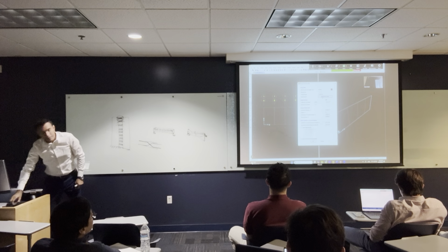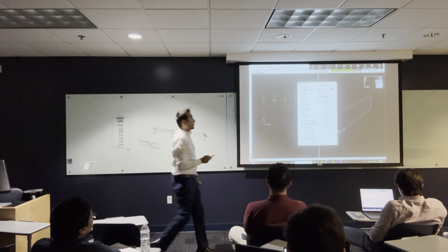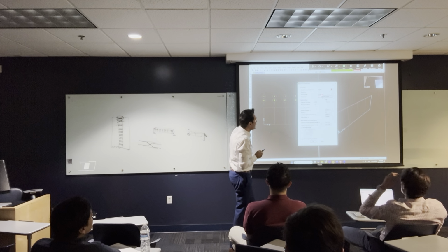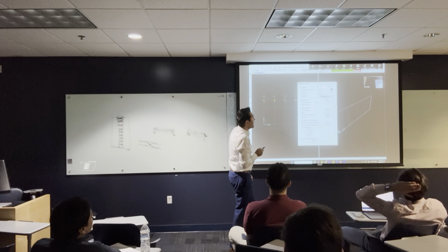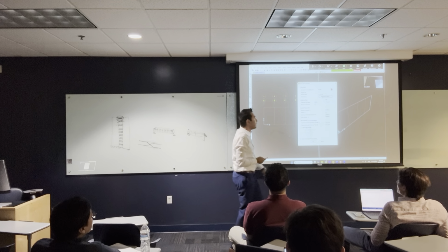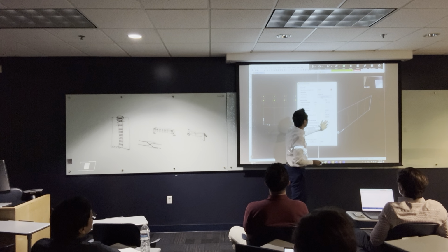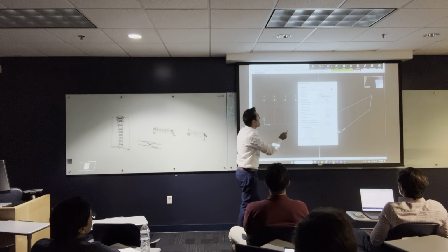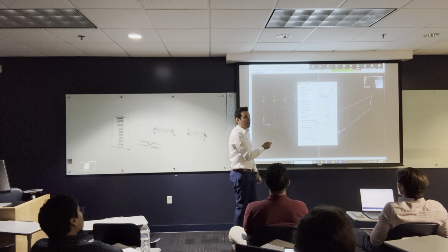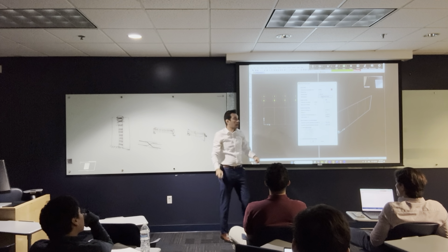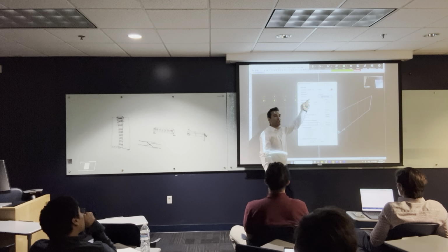You're going to find out that the material name is called 4,000 pound per square inch. The material grade is here. But if the name says that, this doesn't mean anything. Let's say you adjusted this to 5,000 pound per square inch and you said save. This doesn't change the material, because all you're doing is changing the name of the material.